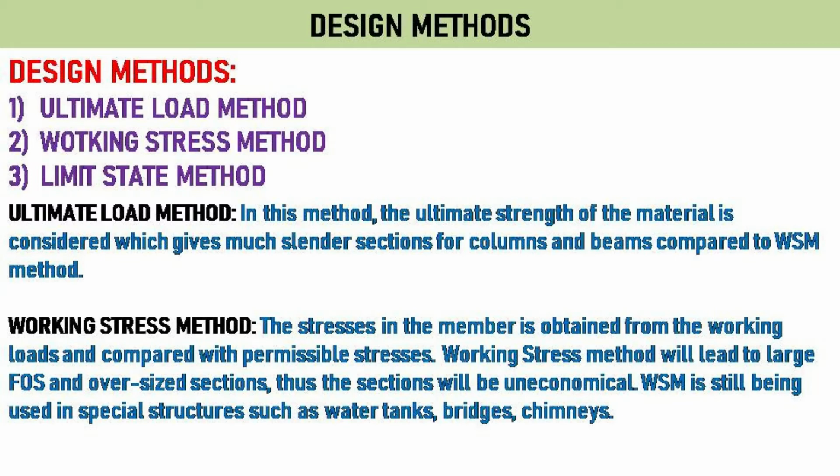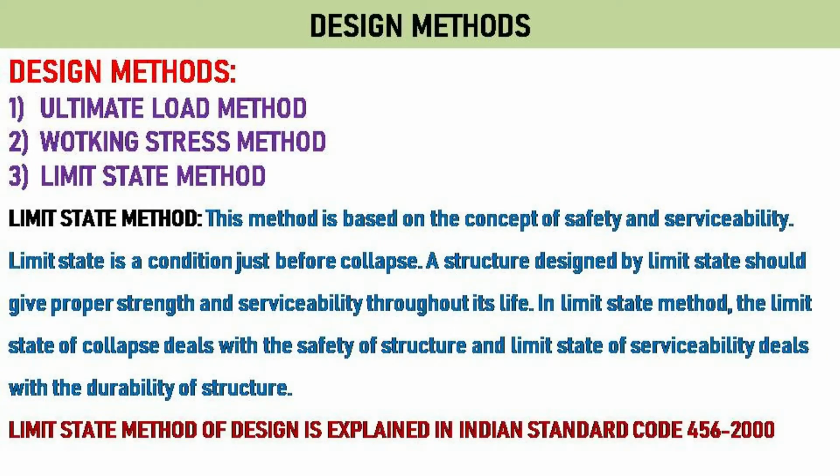In the working stress method, the stresses in the member are obtained from the working loads and compared with permissible stresses. Working stress method will lead to a large factor of safety and oversized sections, thus the sections will be uneconomical. WSM is still being used in special structures such as water tanks, bridges, and chimneys, etc.